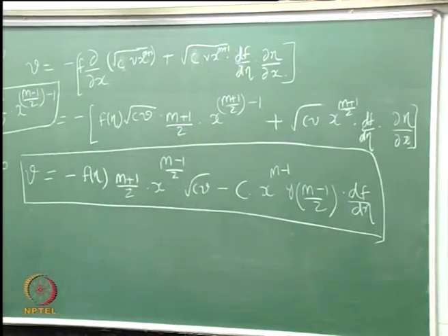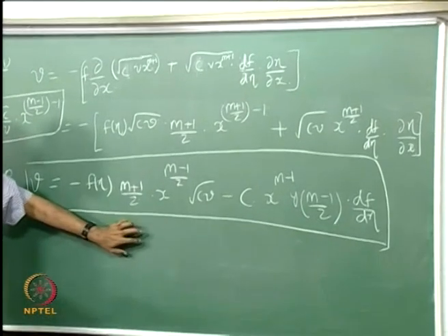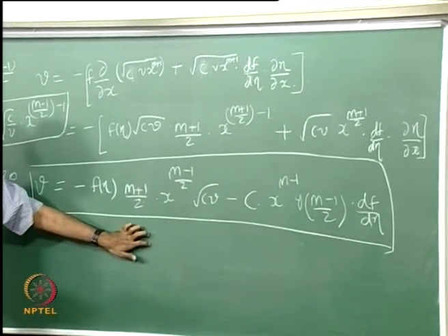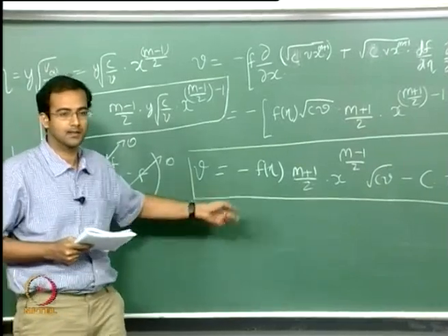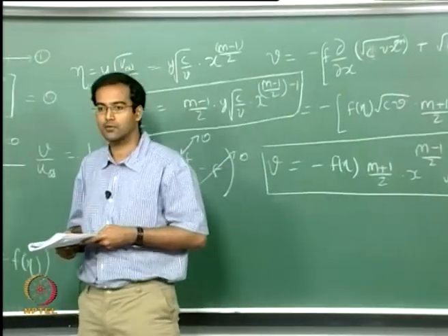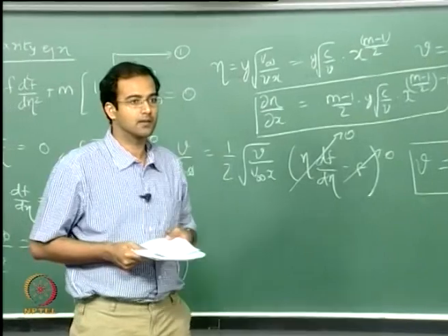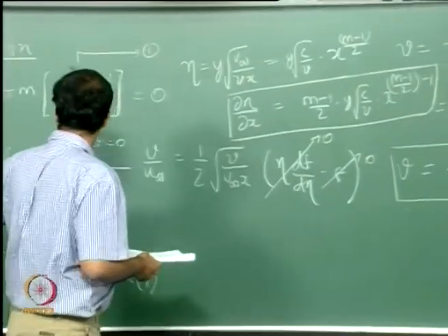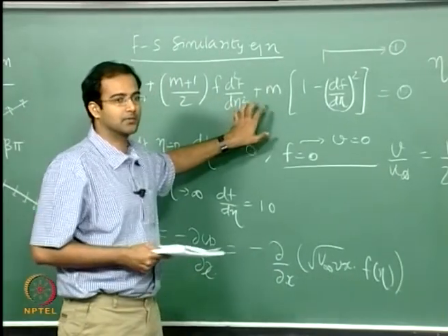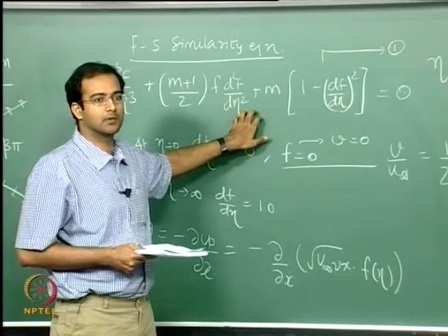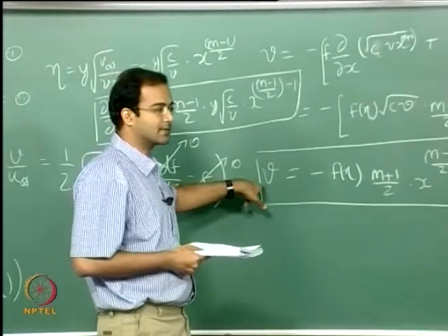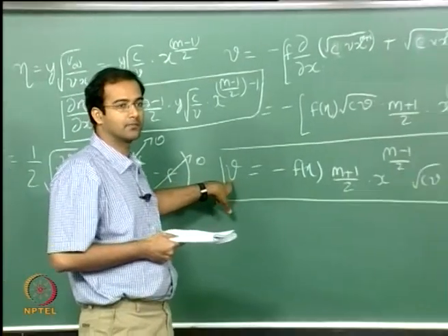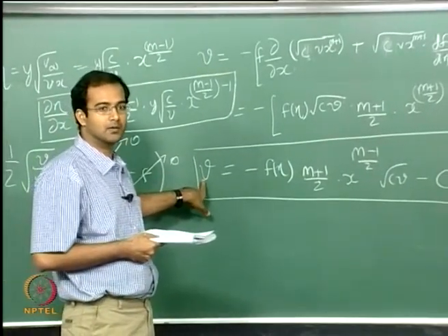In fact, you need to know this when we derive the Falkner-Skan solution. And I think I omitted these steps because I want you to do that yourself. Now I have done that. You can substitute then for u and v into the boundary layer equations, and finally you cancel off all the common terms, you will end up with this equation. Okay, I am doing the same thing now because we are more interested in the v velocity at the wall, therefore I am doing this specifically now.